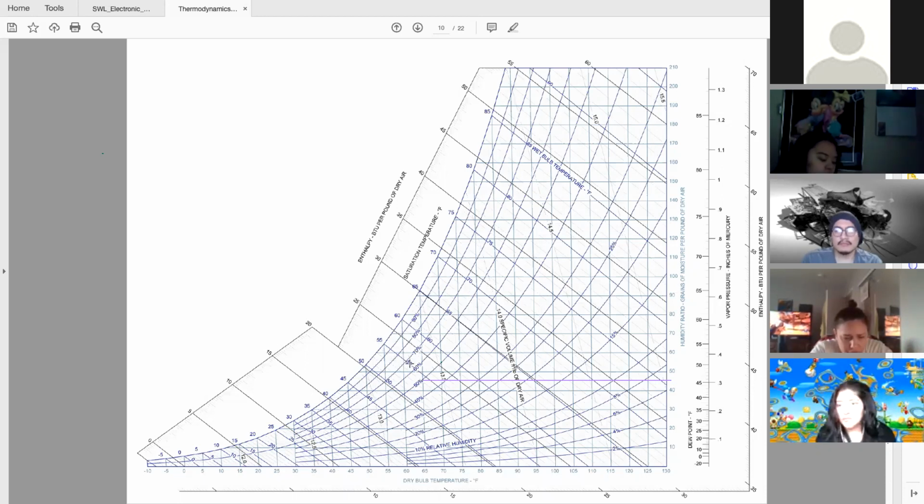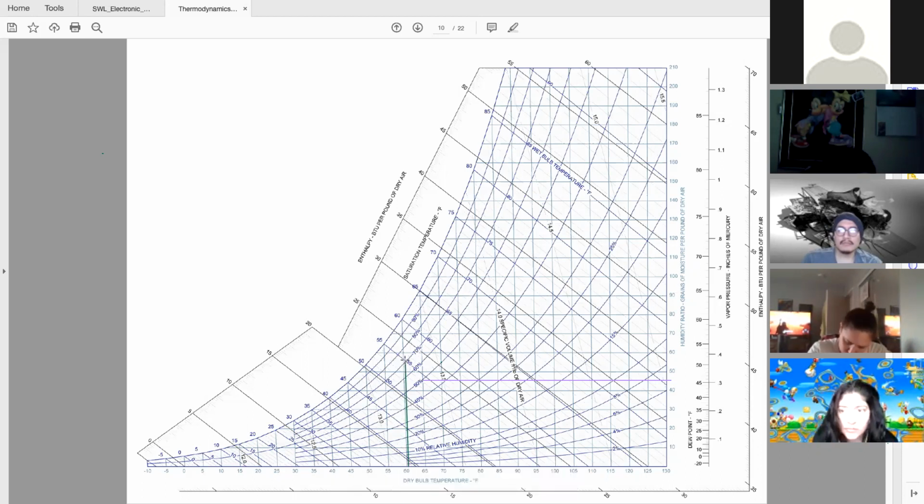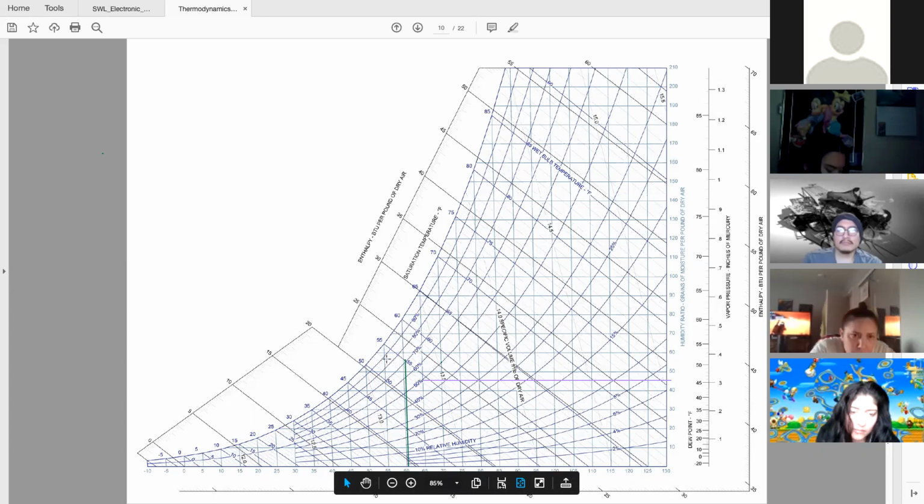We were looking for the wet bulb temperature. So I'm going to just draw a little line here. Let's say we're 61 to 72, and we're just over the 55 line. Oh, okay. I went directly lateral instead of following the line up diagonally.